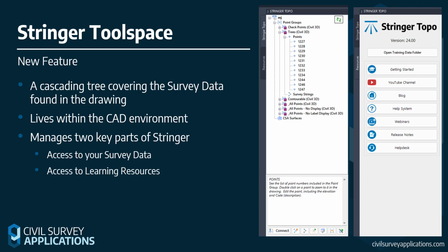This is a brand new feature that allows you to access various objects within your drawing quickly through the use of a toolspace. This is a cascading ribbon that allows you to access different parts of your data from the interface. You can see here I've started with the drawing name before moving down to point groups. Opening that up, I'm given access to all the point groups for the drawing, and I'm able to access both my points and my survey strings.